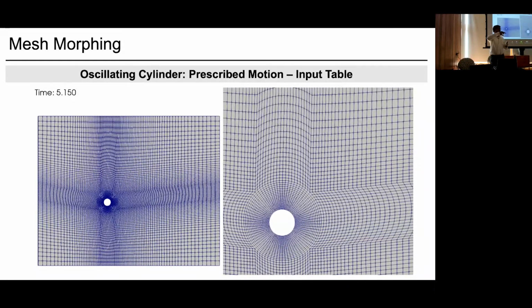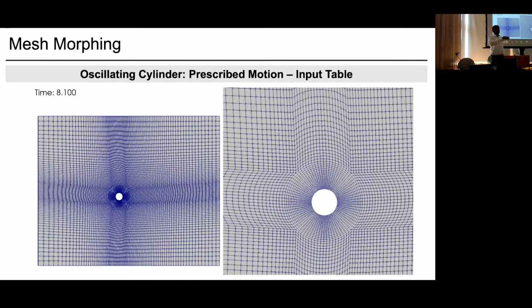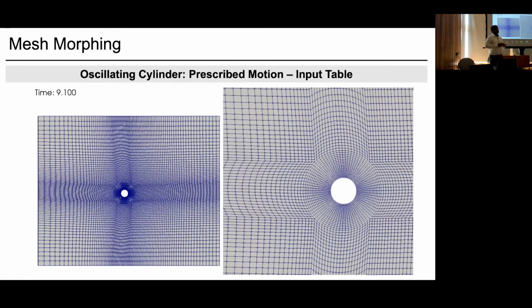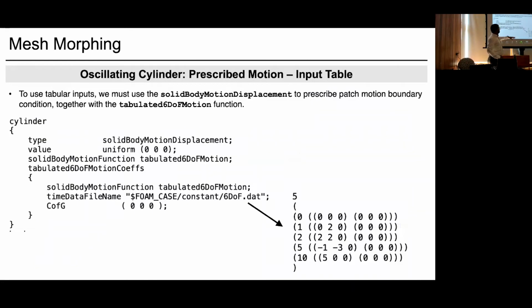So you are mentioning the boundary of the geometry is getting deformed. No, I'm just saying it's rotating like a sliding motion. Yeah, you can do that. So here the third column is the angular displacement, and that can be anything. As far as it is a rigid body problem and the boundary is not deforming, you can give displacement components and the rotational components as a function of time. Sorry, I misunderstood your question.